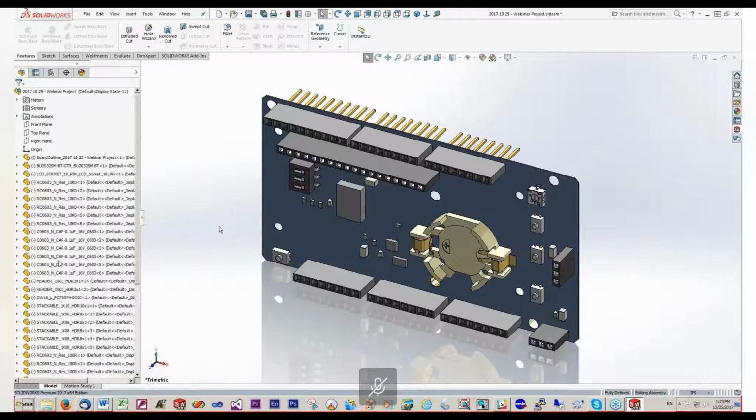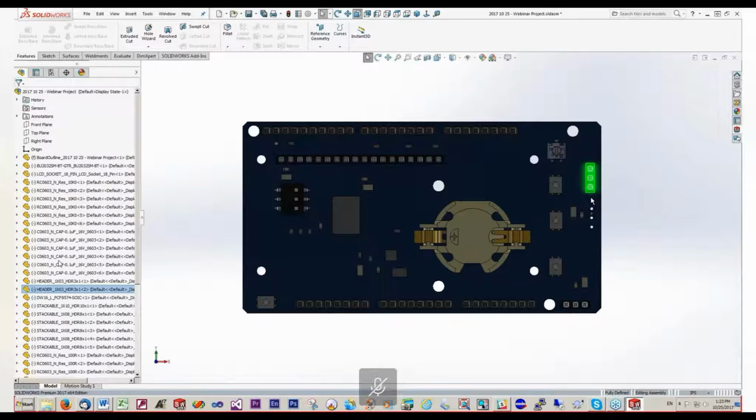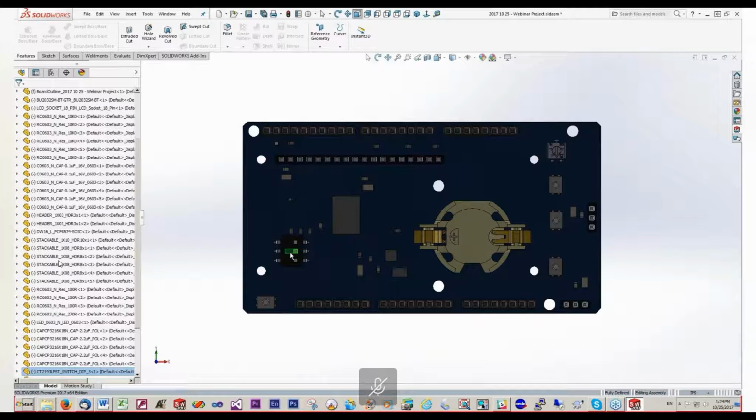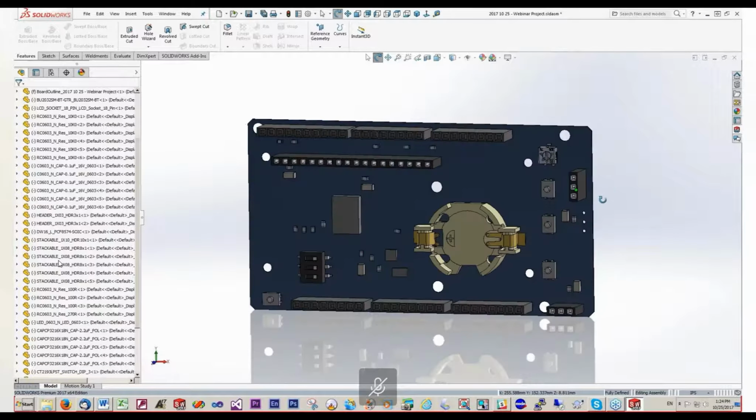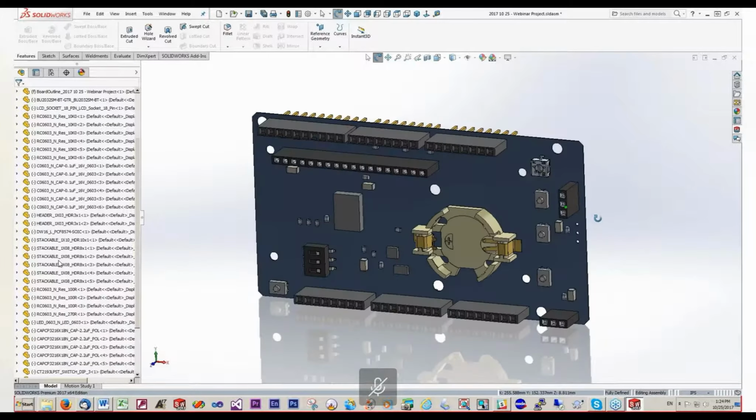What's also nice about this is that we can go the opposite way as well. So now Tom has this on the CAD side, and if he wants to move things and propose some changes, he can do so. The three things that you can change are the board size, you can move components, and you can also add and modify board holes. So what he's going to do right now is move a couple of components. One of them is the switch, and the other one is the H4 header, which holds the sensor. So he's proposing these changes for consideration to the ECAD side here.